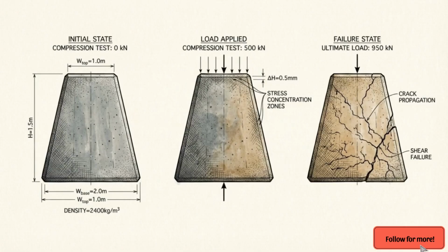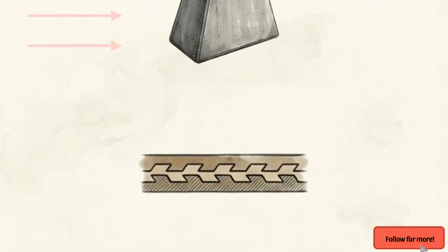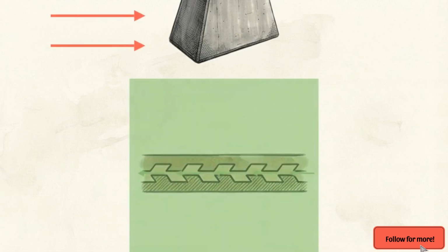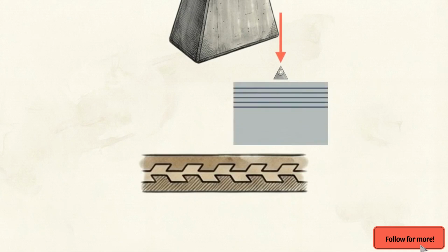All calculated vectors ultimately face 3 final critical geometrical tests, evaluated across both expansion and contraction scenarios. First, this diagram illustrates the sliding check. It verifies that the total horizontal pushing forces are strictly less than the friction of the concrete base against the mountain soil.